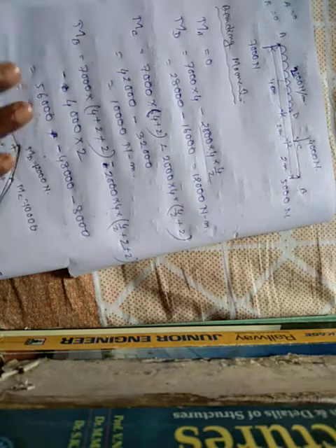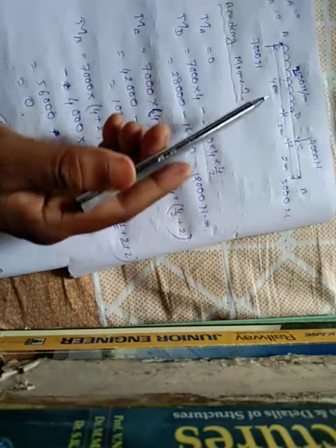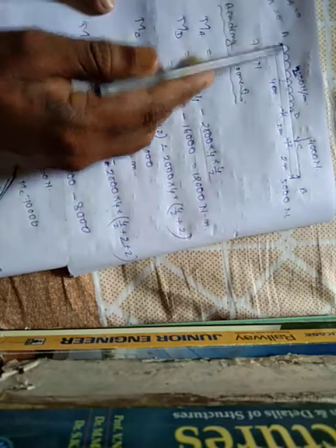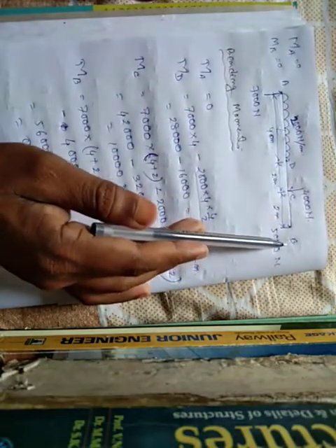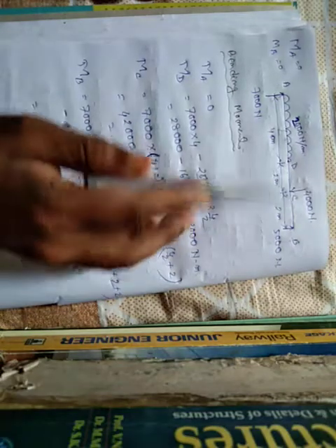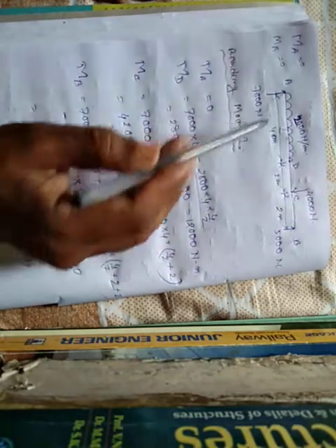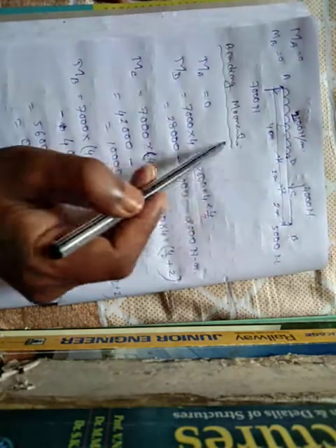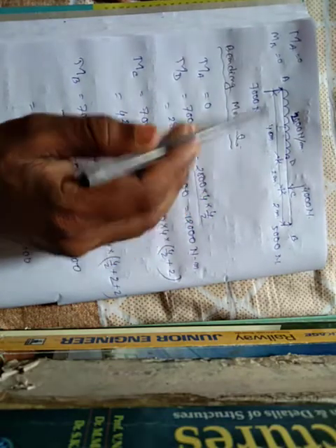Let me give a brief review of the bending moment diagram for the simply supported beam. The bending moment at point A is 0, and at point B is also 0. For a simply supported beam, the bending moment at both supports is 0. The moment about point D from the 7000 upward reaction is clockwise, which is positive, and the uniform distributed load is anti-clockwise, which is negative.